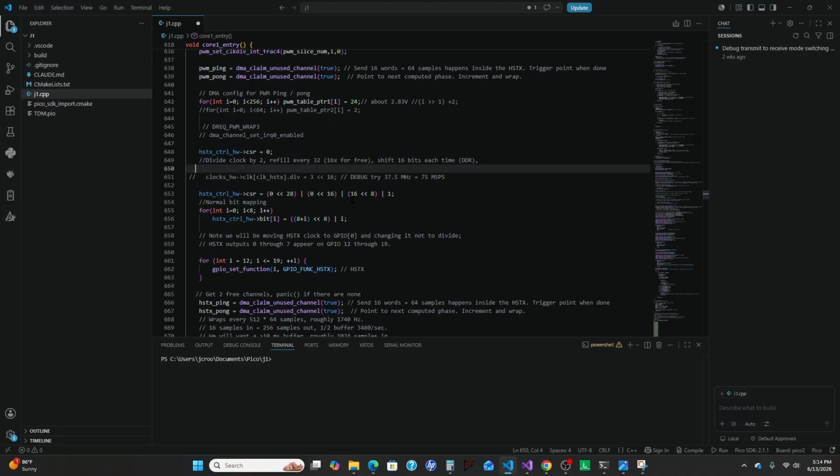You can see there's some hardware registers that have to be written, and we're setting particular register settings so that it repeats automatically up to, I think, exactly 16 times, so that there's very few actual DMA writes that have to occur. It's very lightweight.